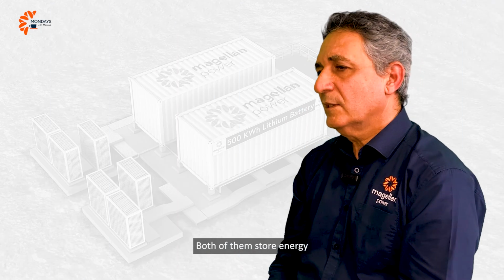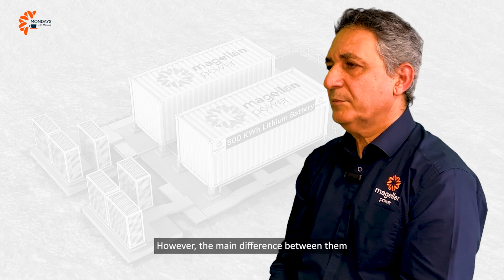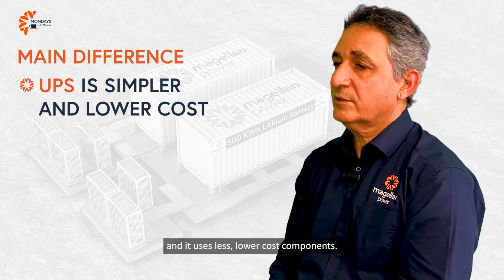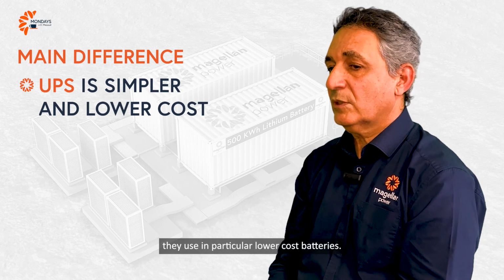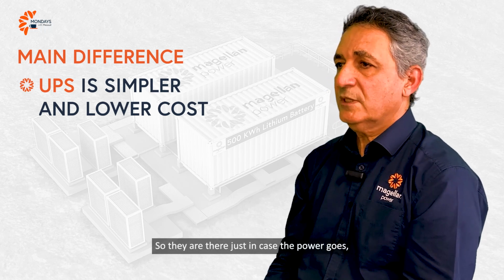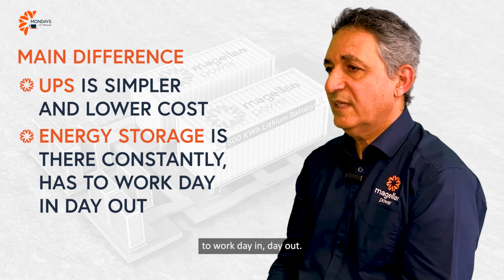Both of them store energy and give energy when it is needed. However, the main difference between them is that a UPS is simpler and it uses lower cost components. They use, in particular, lower cost batteries because they're used for standby application. So they are there just in case the power goes, whereas the energy storage is there constantly and it has to work day in, day out.